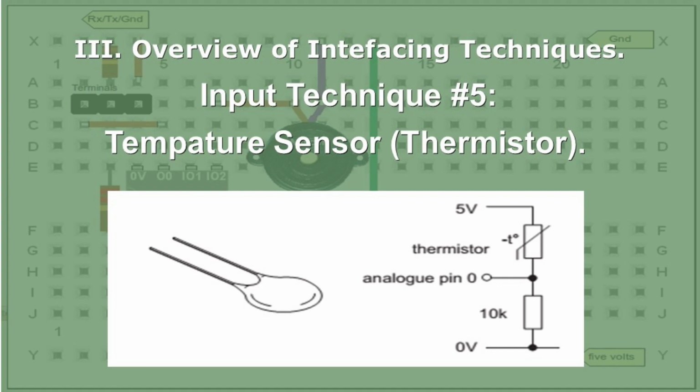Thermistor. Notice that you replace the photoresistor with a thermistor. Notice the circuit is the same, and you can measure temperature with that. Depending on the thermistor, I think the most common design is that as it increases in temperature, the resistance decreases. It's what's called a positive coefficient, I think it is referred to. But yeah, the most common is that the resistance will drop as the temperature increases. They may make some that are the other way around, but that's the most common.